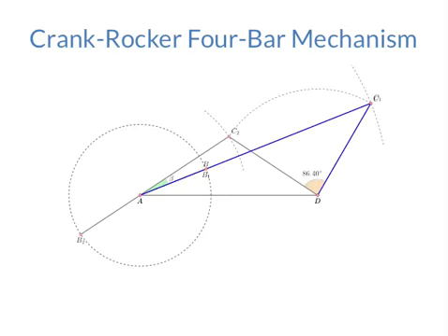Example of full cycle analysis of a 4-bar mechanism. Input link AB rotates a full revolution driven by a motor. Determine the position of all linkages during the complete cycle. For this example, link DC will rock back and forth between fully extended and fully retracted. The angle change of this follower link between the limit positions defines the stroke angle.